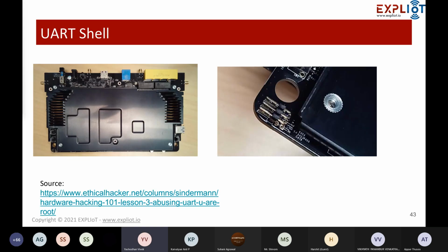Now, the thought process behind accessing the UART shell. Consider, if you have worked on the Raspberry Pi, once you boot up the system there is sudo raspi-config, in which you go and initiate the serial communication. Then, to communicate with the device serially, you find those 4 pins: the voltage pin, the ground pin, and a receive and a transmit pin, which are the standard UART pins.